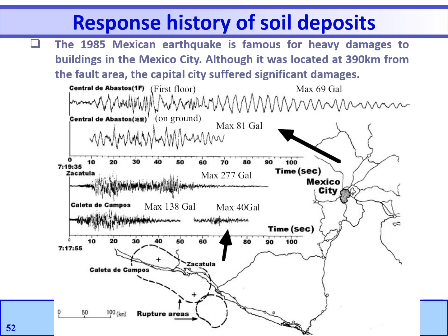We know that ground acceleration varies with time in a highly irregular manner. No matter how irregular, the ground motion is presumed to be known and independent of the structure response. This is equivalent to saying that the foundation soil is rigid, implying no soil structure interaction.